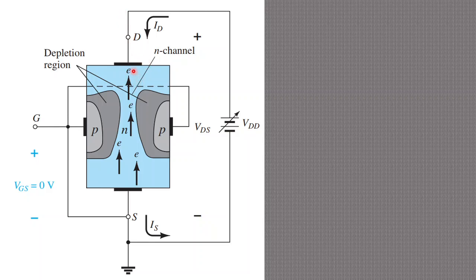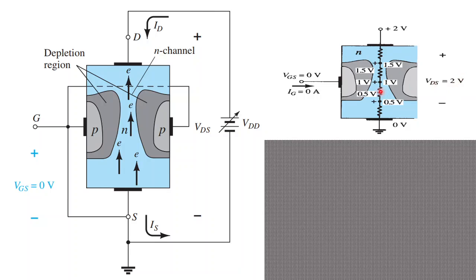This voltage will be decreasing going down. So in this region, this voltage will get lighter or smaller. Imagine VDS is 2 volts, so 2 volts is applied here, but in this sector there is resistance, so the voltage will fall, and this voltage will turn into 1.5 volt here, 1 volt here, 0.5 volt here, at last 0 volt here.